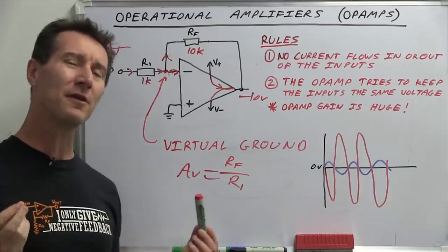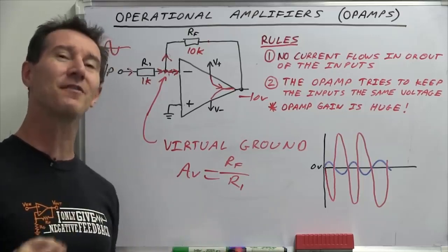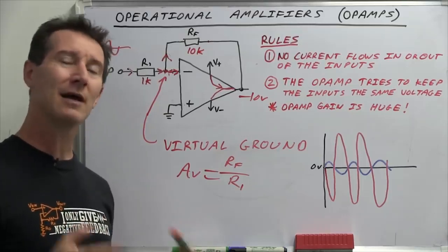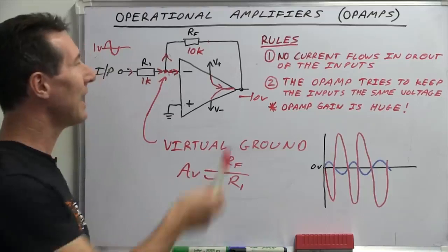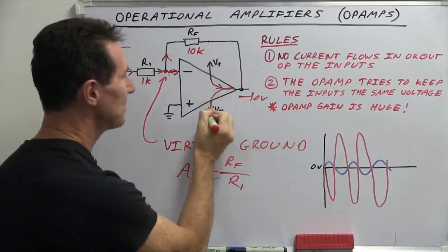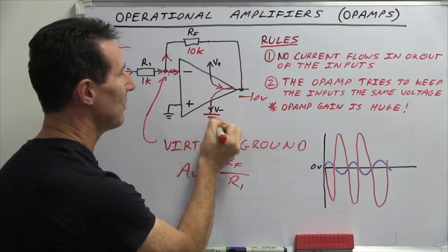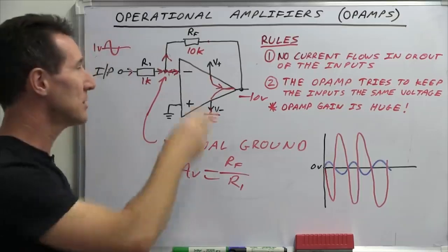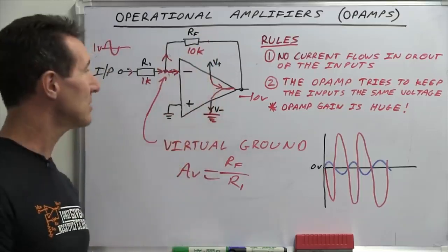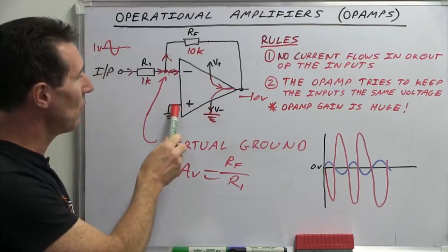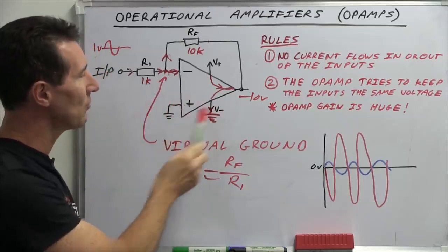Regardless of what the data sheets tell you, there's nothing inherent in op amps that makes them really a single supply op amp. So you can take an op amp that has V plus and V minus and connect this down to ground like that. There's nothing to stop you as long as you meet the minimum voltage specification and don't exceed the maximum, etc. So what happens if we did that in this case? Our non-inverting input is also grounded here.